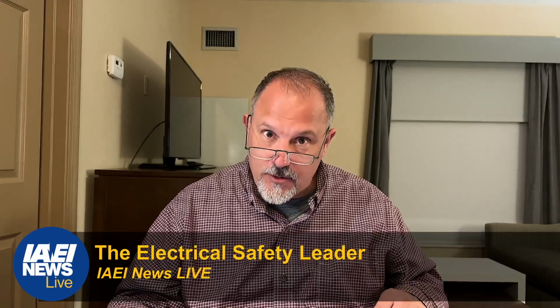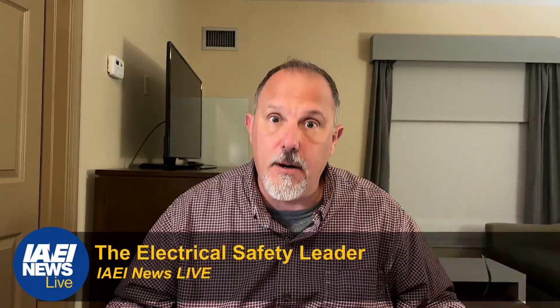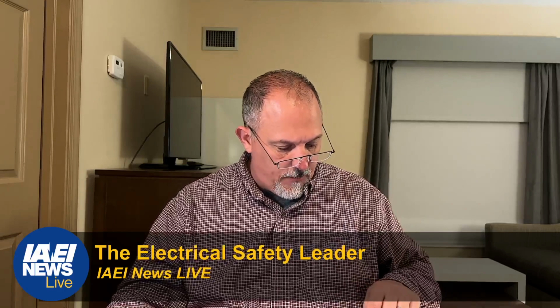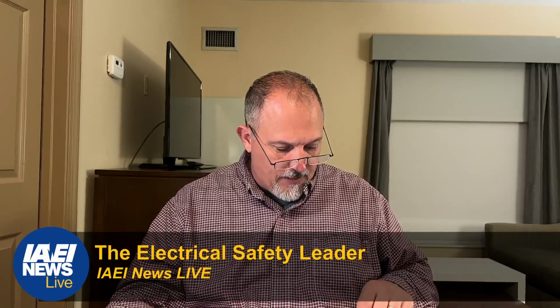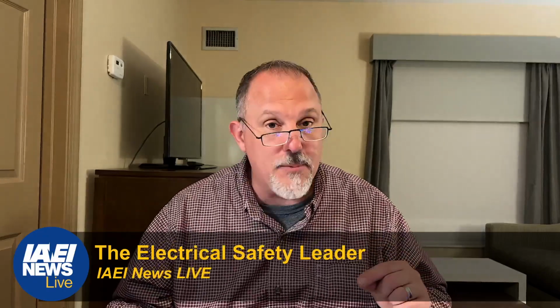Above 150 volts to ground. So this is your higher voltage. Where would you see this? You might see this on pumps, right? Pool pumps, etc., that are 480 volts. Where required in this article, ground fault protection of receptacles and outlets on branch circuits operating at voltages above 150 volts to ground, not exceeding 480 volts phase to phase, single or three phase, shall be provided with special purpose GFCI protection not exceeding 20 milliamps of ground fault current trip.